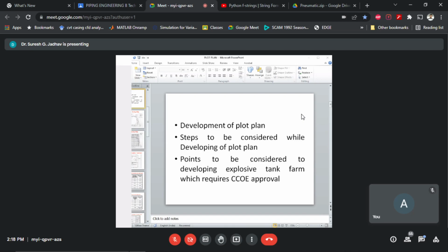In the case of motor conveyances or stationary engines, the capacity of fuel tanks comes under class A. For petroleum class B, it is 25,000 liters, provided it is contained in receptacles not exceeding 1,000 liter capacity. And for petroleum class C, we have to consider 45,000 liters as the quantity above which a license is necessary.